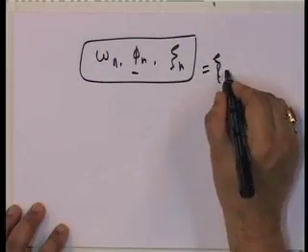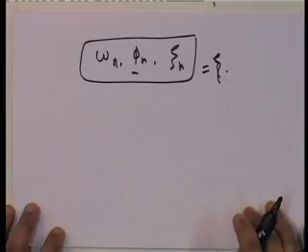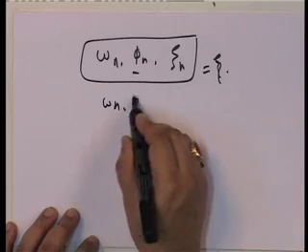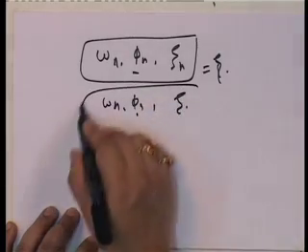So, if we define the xi n, and we also talked about the fact that, since I do not know, I will take that every mode has the same damping. Remember we had discussed that if a structure is made of the same material, then damping is obtained numerically, and it is the same irrespective of whether the structure is a stiff structure or a flexible structure. Damping pretty much remains the same. So, we can just extrapolate that and say that I am going to use omega n, phi n, and I am going to define xi.